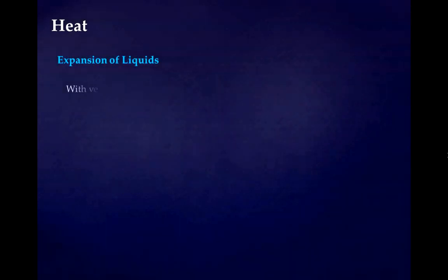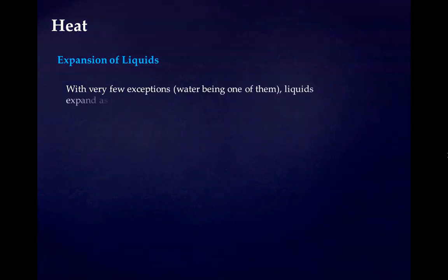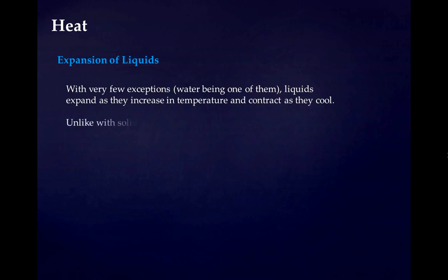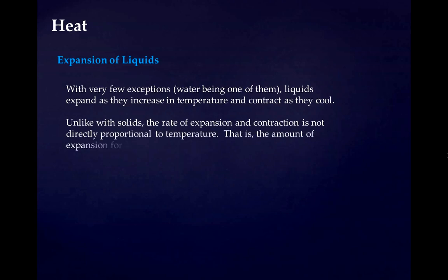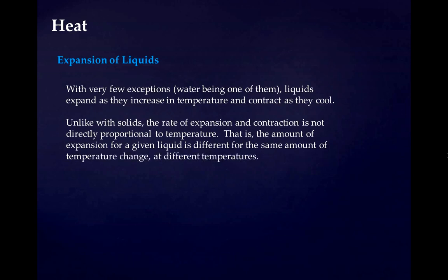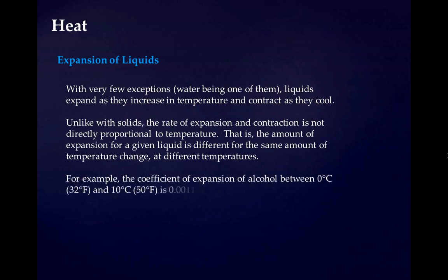Expansion of liquids. With very few exceptions, water being one of them, liquids expand as they increase in temperature and contract as they cool. Unlike with solids, the rate of expansion and contraction is not directly proportional to the temperature. That is, the amount of expansion for a given liquid is different for the same amount of temperature change at different temperatures. For example, the coefficient of expansion of alcohol between 0 degrees Celsius and 10 degrees is 0.0011, but between 10 degrees and 60 degrees, it's 0.0013.